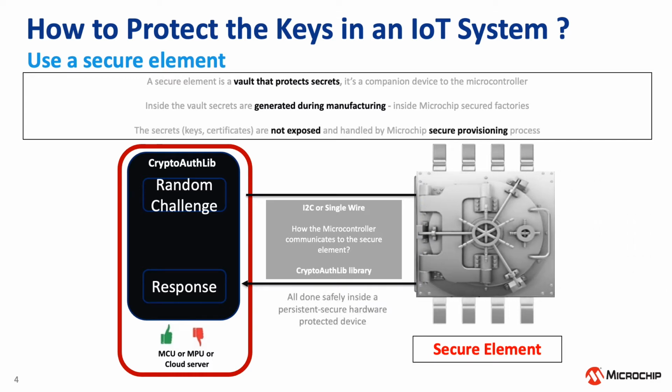What the secure element also brings is that it helps make sure the keys are not exposed at any point in time during development, and especially the manufacturing phase of the product development. That's very important. You could be exposed to operators and test equipment running Linux and network security in your factories, and there are other levels of exposure that secure elements eliminate or try to eliminate. The more you isolate the keys from people, operating systems, and equipment, the better off you'll be. So that's why that becomes a pretty interesting device.